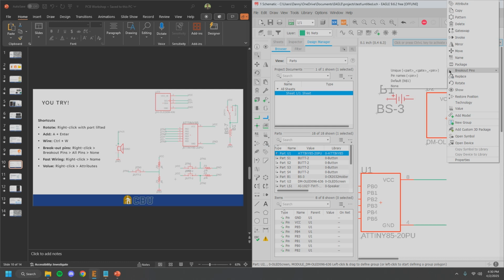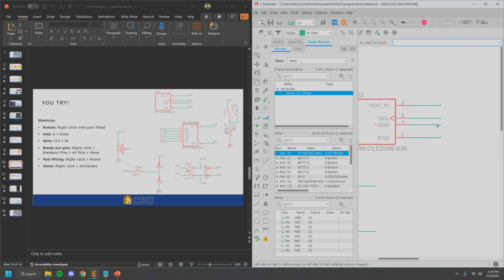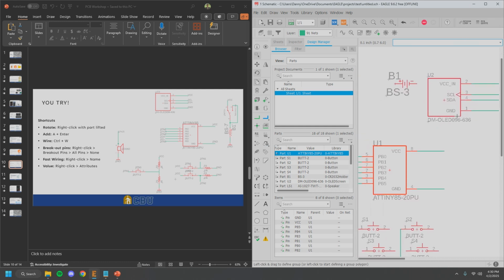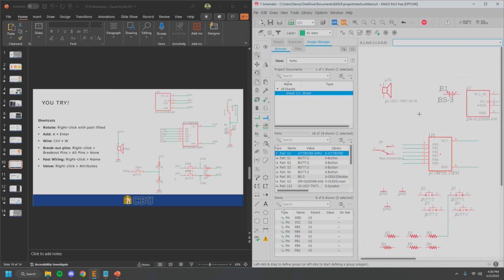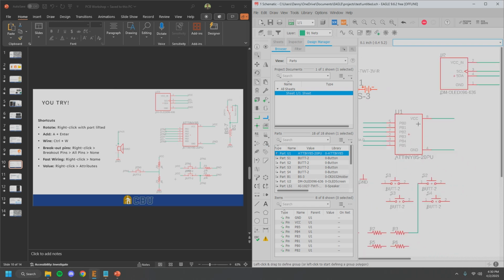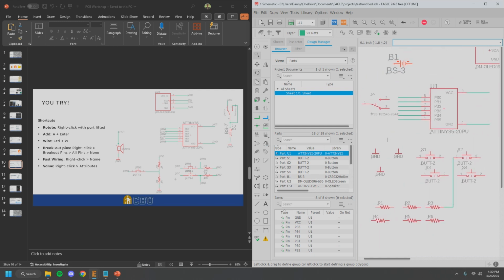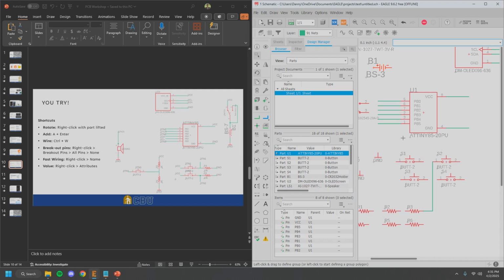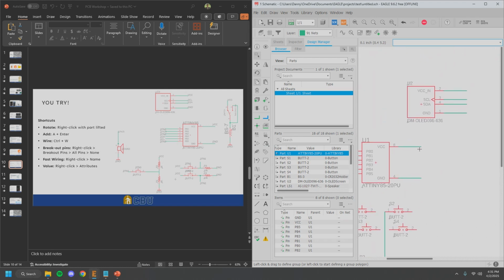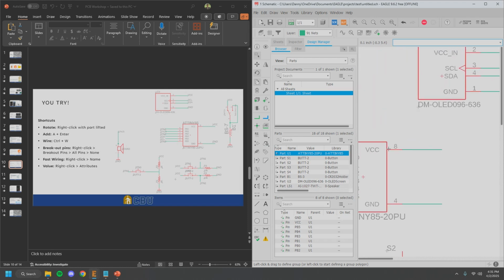If you go to breakout pins, none, that will just output these default wires. Now you might be wondering why we want to do that. The reason is because instead of having to physically wire up every single one of these pieces, and they might just make an absolute rat's nest of crossing each other, what you can do is, for example, with the VCC pin here, right click and click name, and we name this VCC. It'll say, hey, where do you want to place the label? This part isn't the important part.